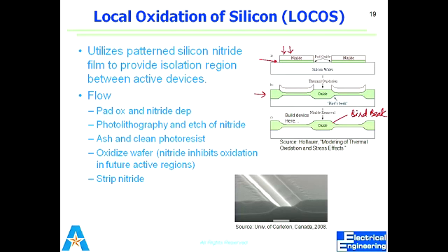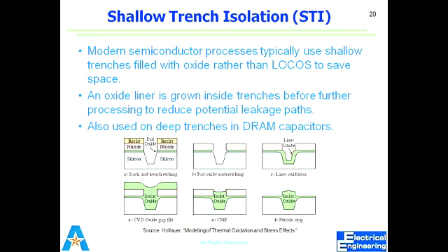So active area should be at least 2 times the thickness of the field oxide, at least more than 2 times the thickness of the field oxide. So if the field oxide is 500, it encroaches 500 from this side, 500 nanometer from this side. If it's 1 micrometer, it means nothing left. 1 micrometer is equal to 2 times the field oxide thickness, so there would be no active area. So my active area should be large enough. Maybe we have not mentioned on this slide, but the active area should be large to avoid this.